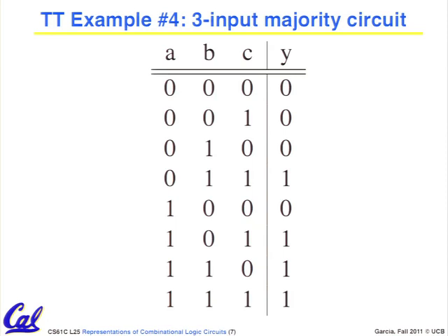That's good stuff. So this is a majority circuit in which you basically have three of you. Who's ever played this game where you want to choose among three of you, and you go like rock, paper, scissors, shoot. You either put a 1 or a 0, and then whoever happens to be the odd person out gets chosen to go downstairs to get the pizza you ordered or something. So look at this. This is the majority, right? If all of them are zeros, it's 0. If the 1's an outlier, then the 0 is the majority and 0 wins. If 2 out of the 3 are 1s, then a 1 wins. It's kind of cool, right? It's a majority circuit.